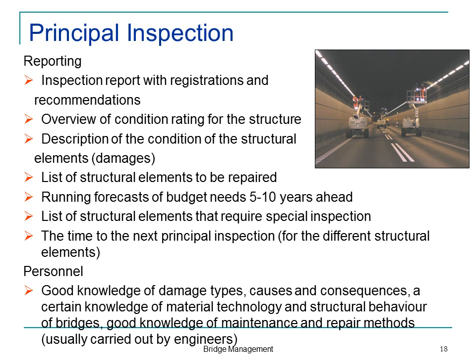But anyway, the report recommends you give a condition rating of the structure. We have a scale from 1 to 5. 1 is perfect, 5 is, well, it should be closed right now. You will also give a rating of how fast you think the deterioration is going to go.